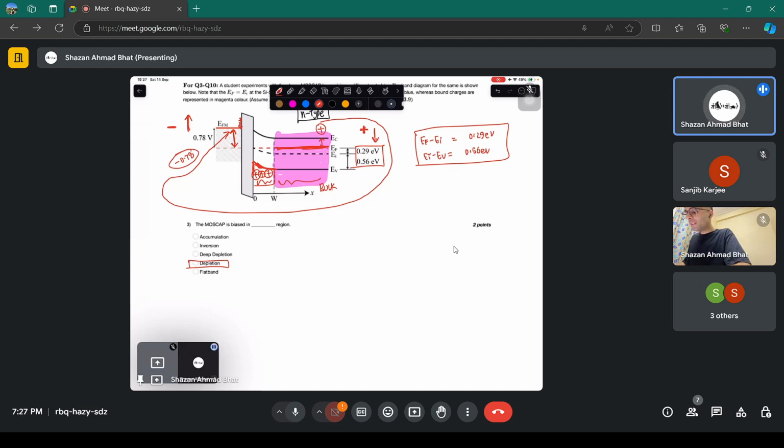Now, there would have been another scenario. There is one more important point. This particular Fermi level is just touching the intrinsic level at the surface. This is the key indication of the depletion region, because it is showing you that EI in bulk minus EF, divided by q, is equivalent to something called the Fermi potential.